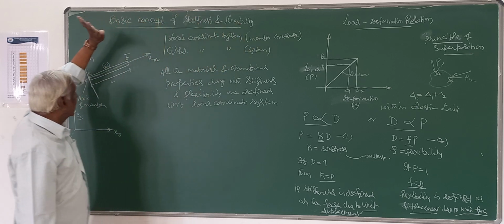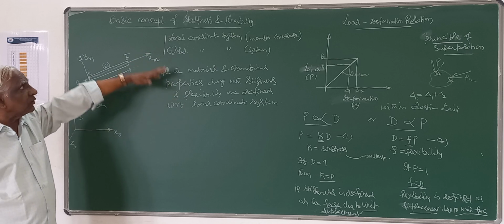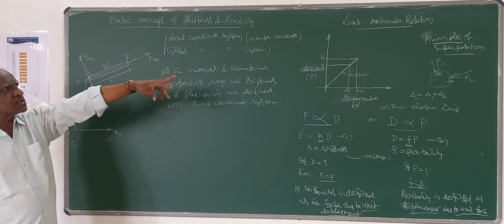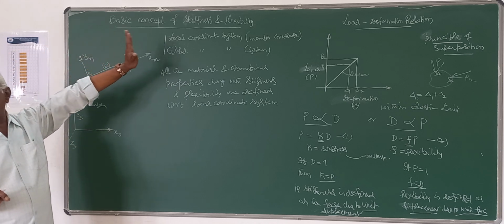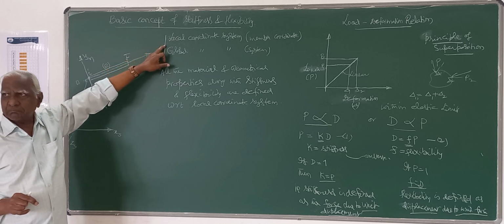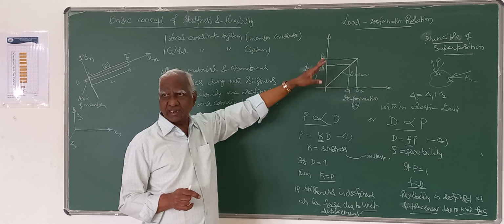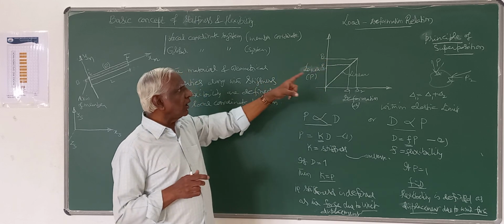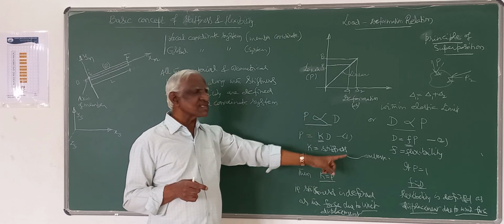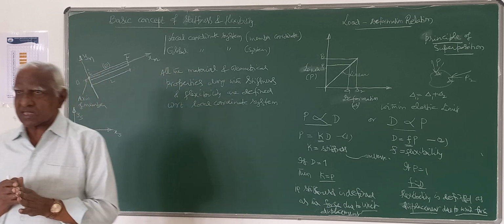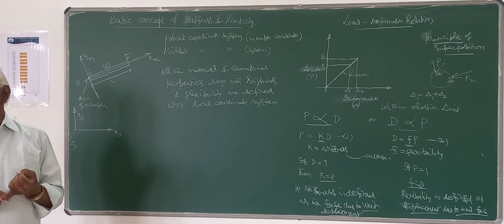So the important points to be remembered are one-dimensional structure and its local coordinate system. Only with respect to that do we define stiffness, flexibility, force, and displacement. Because force and displacement are vectors, we need to define the direction, and that direction is always with respect to the local coordinate system. The load and deflection, which are vector quantities, give a linear relationship within the elastic limit, where the principle of superposition is valid, so we can define stiffness and flexibility as fundamental properties of the material associated with all members of the structure, which helps us in doing the analysis.